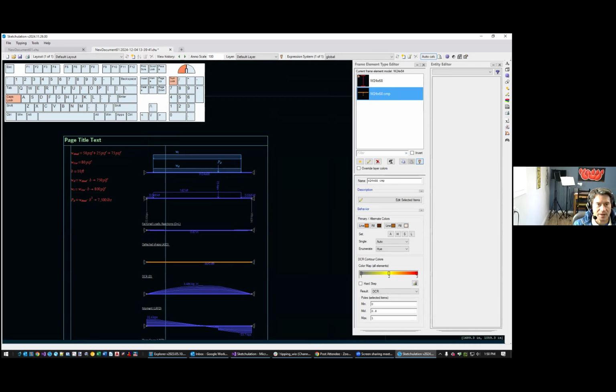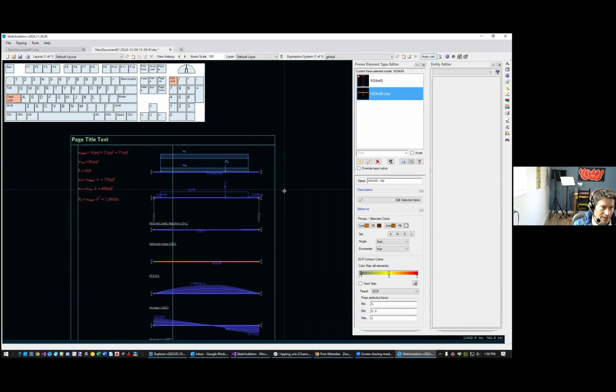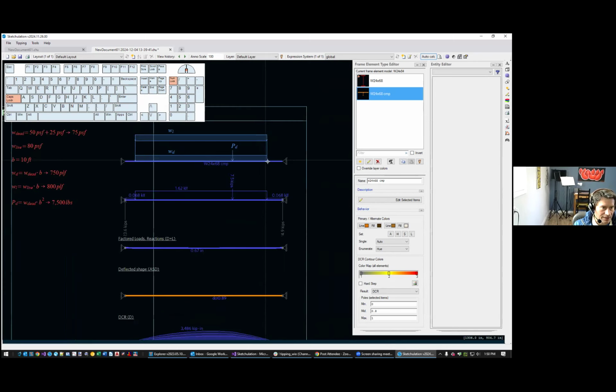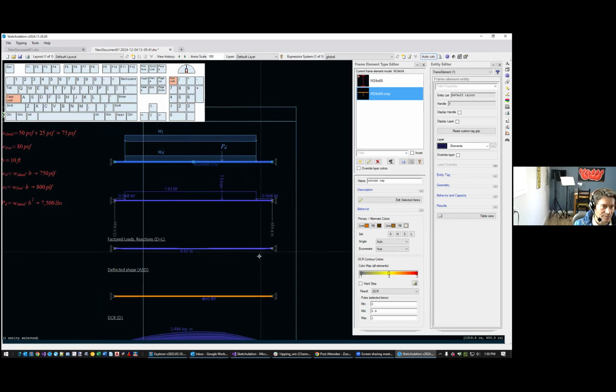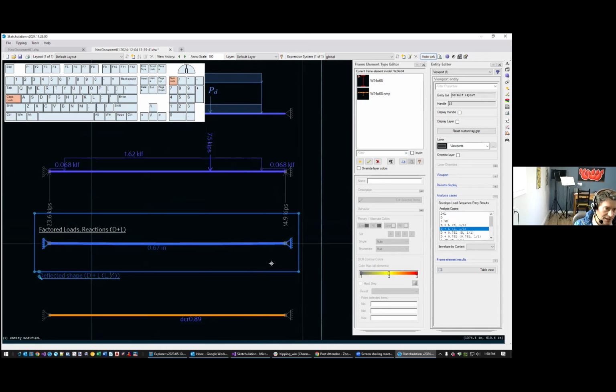And now I can paint this onto here and type F5, and we see the frame element type has set up with this W24 by 68 composite, and immediately I'm a little confused. I was wondering why my dead plus live load didn't change much. It should have reduced the deflection if my composite action was very effective. And so I'm wondering, okay, what's going on?